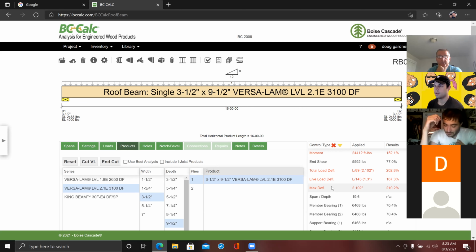Couldn't I use steel instead, which maybe gives me a stronger E value, and then maybe this size beam would work. But remember, the I value was the one that had to do with the shape of the beam. And so that's the easiest one to change, is the I value, which is like just choose a bigger beam. That doesn't require any changes of design and so forth. And then I can still use the same material. But yeah, it's E and I that you actually really have control over. And so, yeah, let's go back and, you know, choose a different beam.